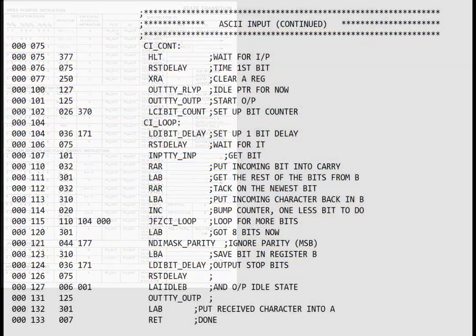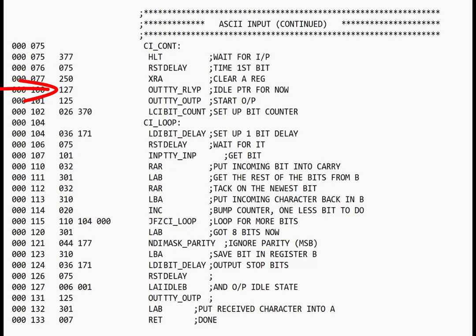When the processor is working on that one line of our assembly code, whether it be 1 byte, 2 bytes, or 3 bytes, it retrieves and handles these bytes in that line one at a time. So it gets the first byte and it deals with it. The processor now knows if there's another byte. If there is another byte, it gets that byte and it deals with it. And then if there's a third byte, it'll read that byte and deal with it. So it deals with these bytes sequentially one at a time.